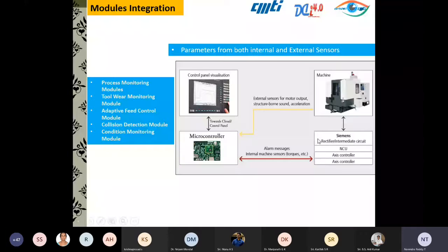Now, with the help of machine-to-machine connectivity, like OPC, you can get all the information which is there in the CNC controller. You can read it, like alarms, machine information, all the configuration parameters which have been used, like what feed, what kind of motor, the current consumption. Then you can also show the alarms, warnings, your positions, the feed rate, spindle speeds, all that information you can get from here. But the only limitation, even though you are getting the complete machine information, around 5,500 parameters you can read from this controller, is the speed at which it gives the data.